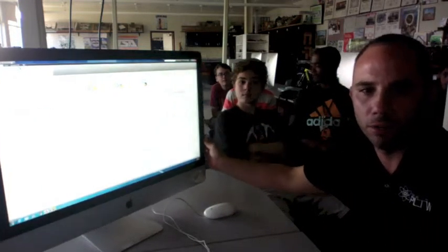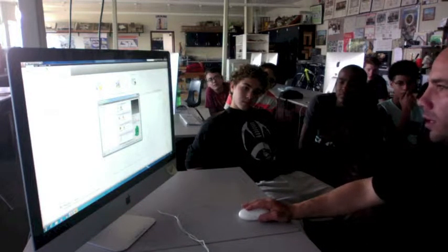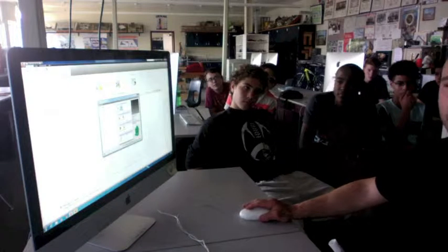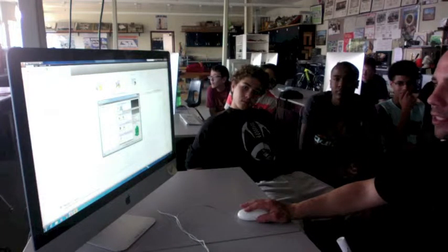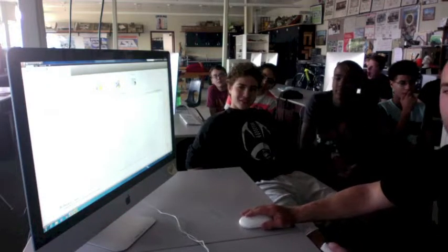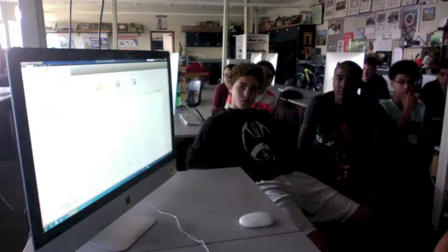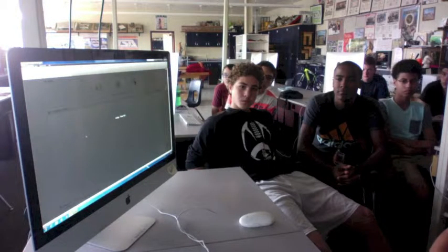Alright, so it's kind of hard to see. Make sure you can see the computer. But the first thing we're going to do is go to a new file, right? And when you click new, the first thing you do is pick a standard part. So I'm going to pick standard part, and I'm going to hit create. And it brings me up to that general screen where it says I want to start my new sketch.